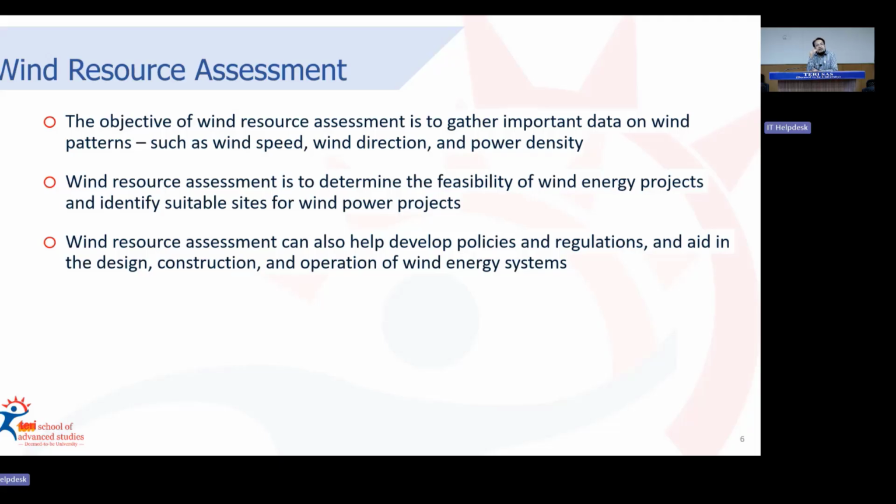So wind resource assessment, as I have earlier indicated, is basically the process to determine the wind at a particular location and evaluate the available wind in order to assess its suitability to be converted into wind power generated electricity. The objective of a wind resource assessment is basically to gather important data on wind patterns, such as wind speed, wind direction, and the generated power density.